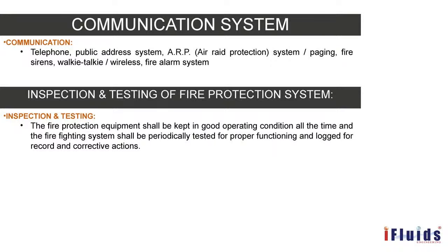Then chapter 16 states the inspection and testing of fire protection systems. It is stated that the fire protection system should be kept in good operating condition at all times. It has to be periodically tested for proper functioning and logged for record and corrective actions. The key timings mentioned here: if it is a fire water tank or reservoir, it has to be inspected externally and internally as per OISD standard 129. The water reservoir should be emptied out and cleaned once in 3 years. That is the mandatory condition mentioned here.